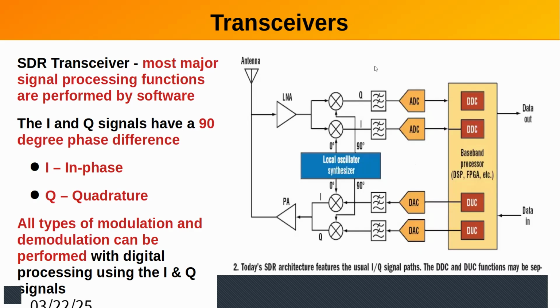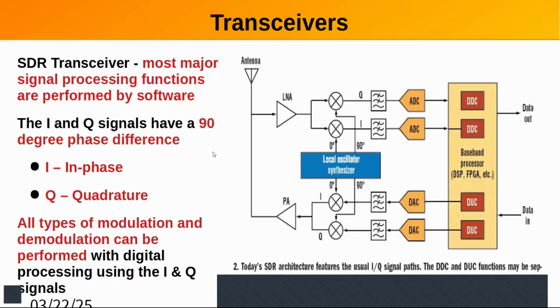In a direct conversion, this I and Q typically is generated within the processing, so you're feeding the signal directly into an analog to digital converter and then operating on it in the digital world. This radio is kind of a hybrid. It uses what's called a Tayloe detector to generate the I and Q signals by sampling at 4 times the signal rate plus the offset of the IF.